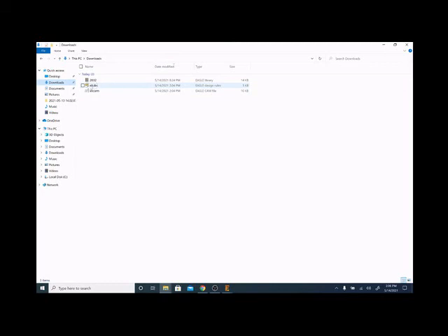All right, in my downloads folder, we can see the elc.drc file. I'm going to open up my documents, Eagle, and right here I have my design rules and my CAM. So I'm just going to drag DRC into my design rules and my ELC CAM into my CAM folder.